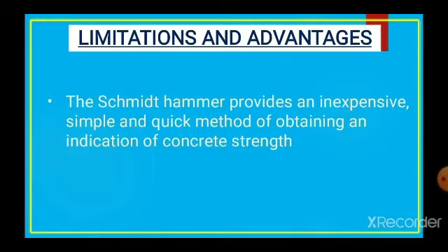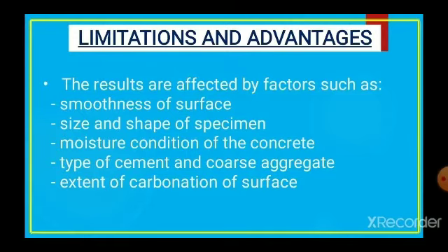The limitation is that the results are affected by factors such as smoothness of surface, size and shape of specimen, moisture condition of the concrete, type of cement and coarse aggregate, and extent of carbonation of surface.